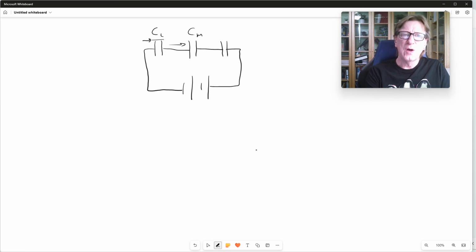So how would the current through here compare? They actually have to be the same. And we'll deal more with this later on, but that's called the charge continuity principle. And it's because charge is a thing. It can't just vanish. And so any current that comes in here, any charge that comes through here, also has to be through here. So it's got to be the same. I've got to have the same amount going all the way across here. So now when you look at the next one, we compare the middle to the right. Well, okay, those have to be the same too, because it's coming through.